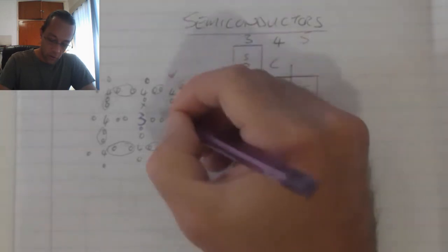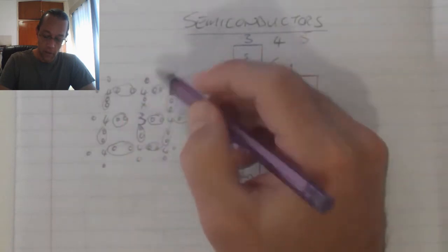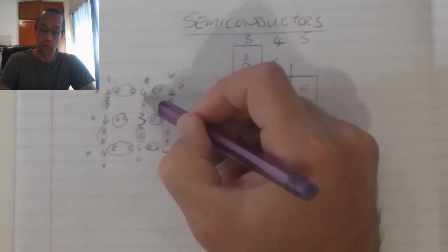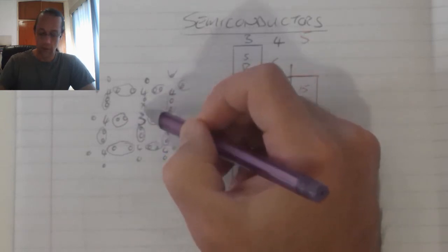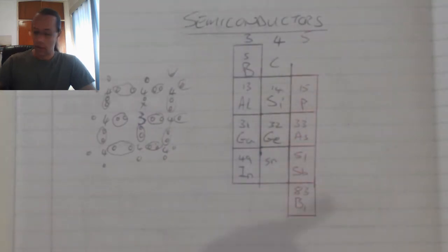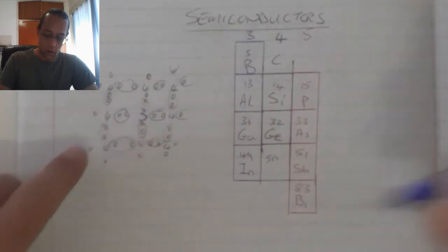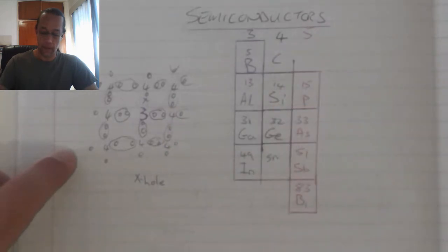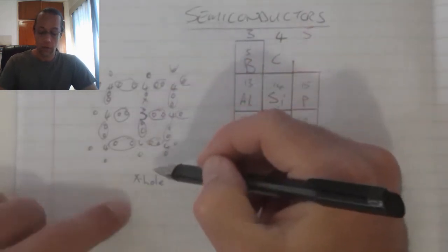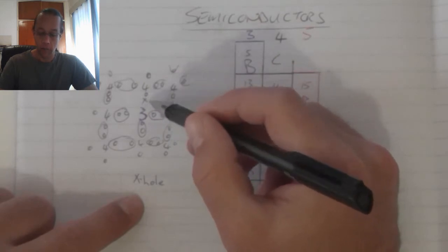And those 3 electrons will bond with 3 of the elements around it, but we see over on one of the 4 sides that there's an electron that doesn't pair bond with my column 3 element. Now, that place where the electron can go, we call a hole. Okay. Now, that hole is just a place where there is space for an electron.